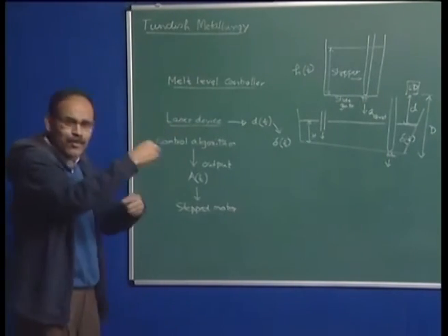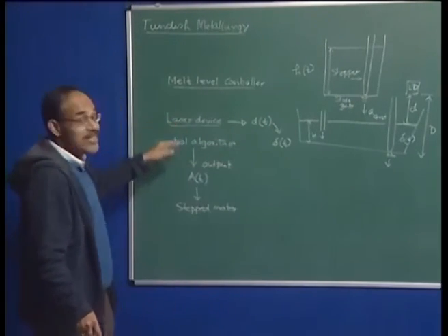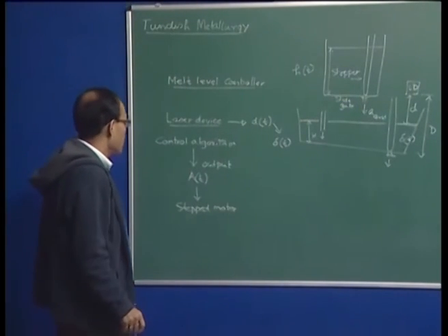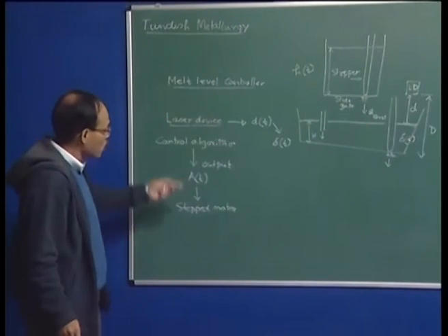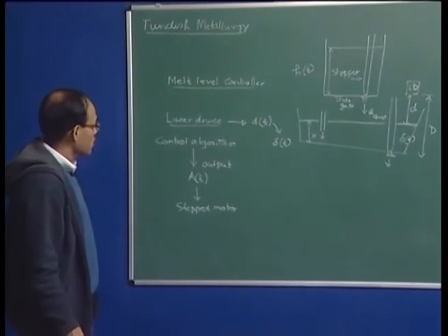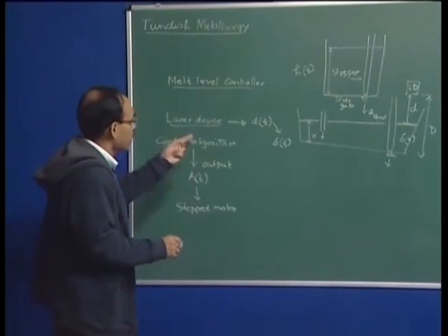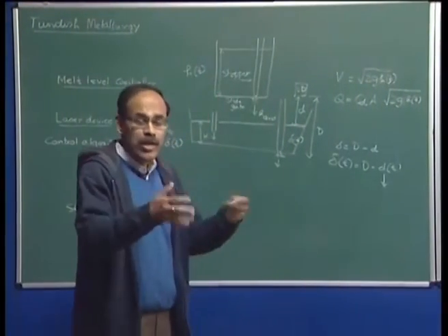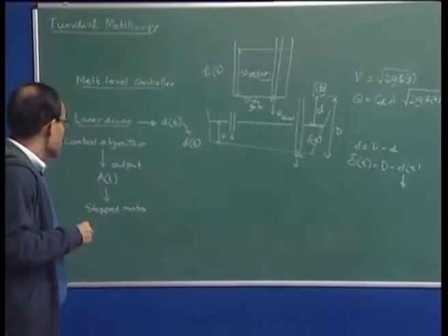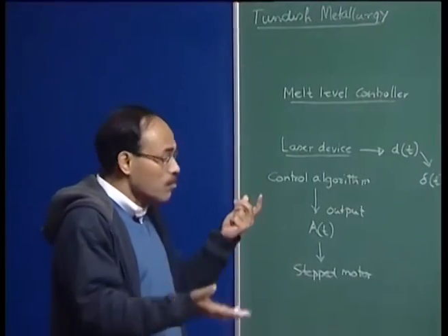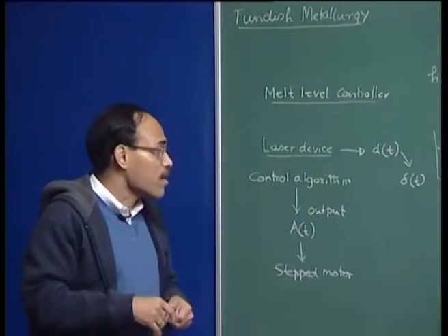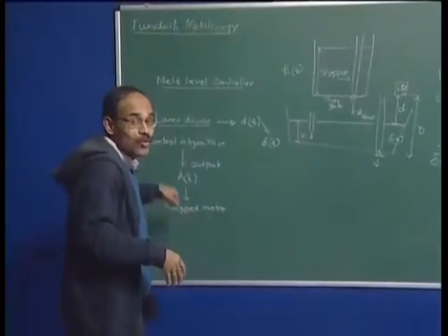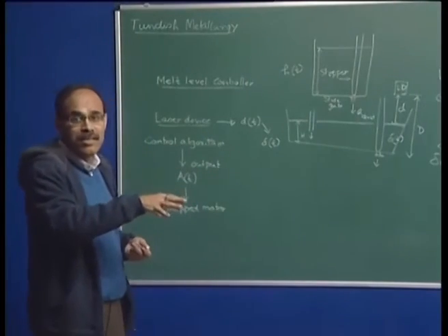So, this type of simple process control in a steel making shop, which we will call dynamic control of the tundish bath depth, is a very simple control algorithm, or melt level control procedure, that I have illustrated. But there are much more sophisticated control algorithms which are available in the BOF shop, which are available in the continuous casting house, where most of the processes, the fluctuation of the mold or the decarburization rate in oxygen steel making converters, are being controlled, and everywhere we will see that extensive process control is being applied either in an offline fashion or in an online fashion.